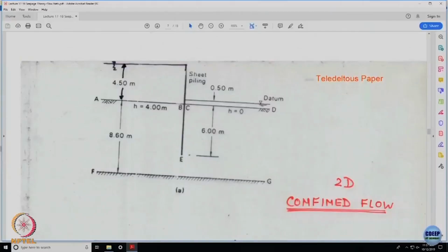Clear? So, this is how conventional geomechanics is getting transformed into the latest solutions. What I need is a very high strength sheet pile, that is it. So, whatever my embankment was doing in terms of retention of water, I can achieve it by simply inserting an element up to a certain depth, fine.